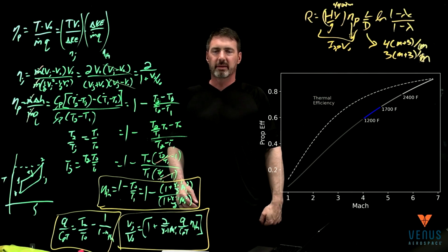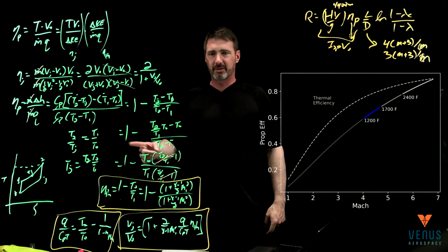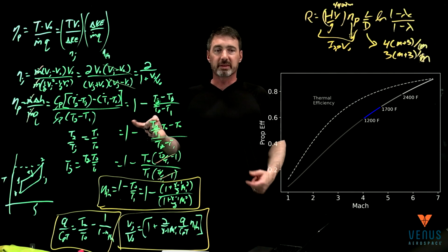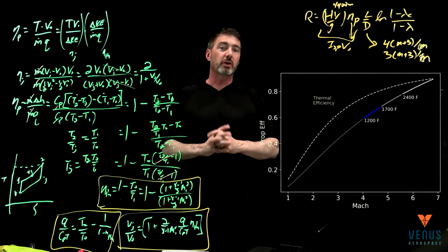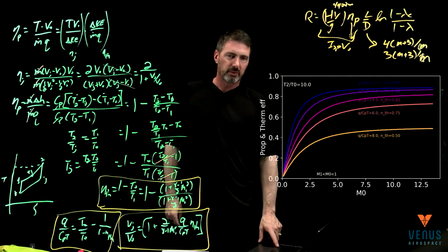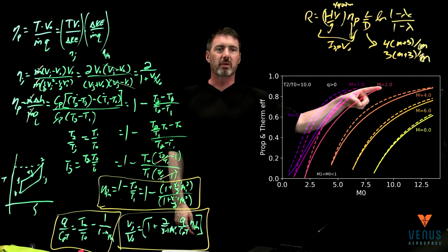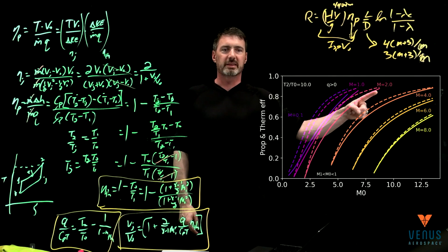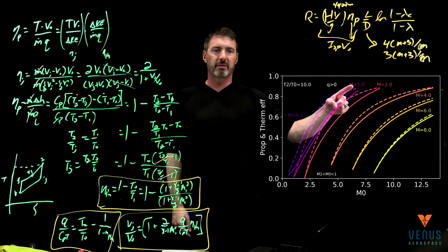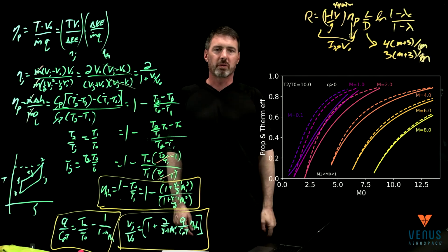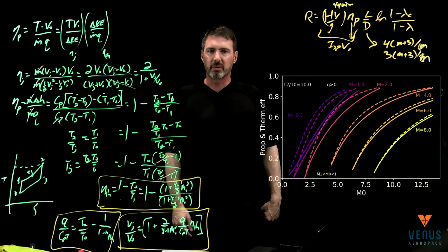So if you wanted to do ramjet at Mach 14, you'd have to weigh up your temperature limits. It also then says, if you go redo this with scram, which is kind of what you're seeing here, you could come back and pick, no, let me go combust at Mach 2. It's going to extend that speed, right? So as opposed to cutting off at shorter Mach numbers, it would get you further down the road.